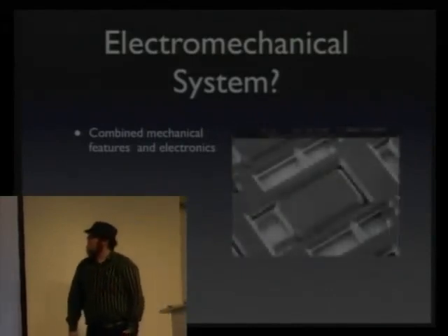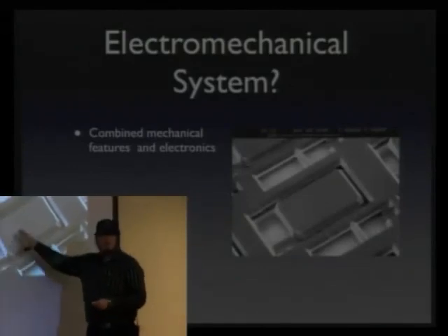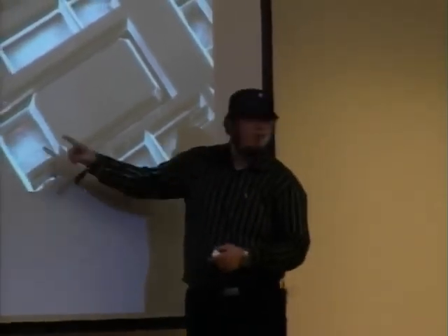This is a standard accelerometer, with a cantilever with a seismic mass on the end. When you move it up or down, this mass is always a little bit slower. It takes longer to accelerate, so it will bend, and then you measure the bending.